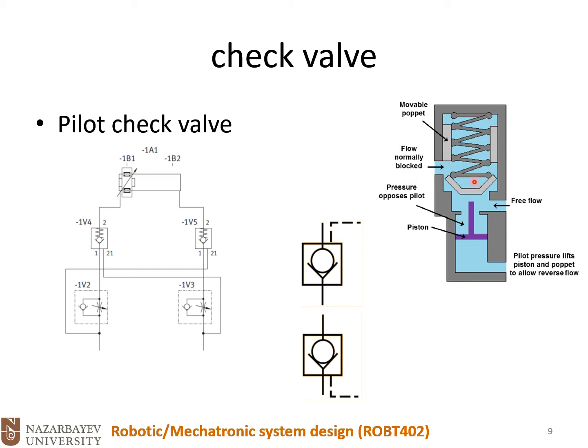Okay, so this is how it works on pilot control valves. When we say we have a pilot valve, it means we have a separate pathway for the air, and that pathway is solely used for sending a signal to either activate, open, or close the valve, depending on the application. We have one pneumatic circuit here. We will discuss it more as we go forward, and we will simulate it.